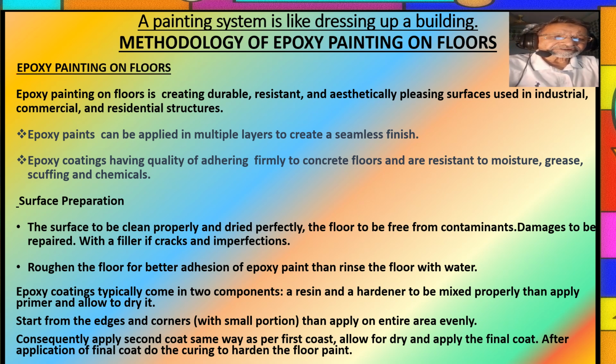We are going to take the following guidelines for the safety throughout the resin. The floor will be washed with water to neutralize the acid and allow the surface to completely dry. Mixing, how to mix the epoxy resin and hardener. Resin and hardener must be mixed thoroughly to activate the chemical reaction that causes the epoxy to harden, so that the mixture is homogeneous.